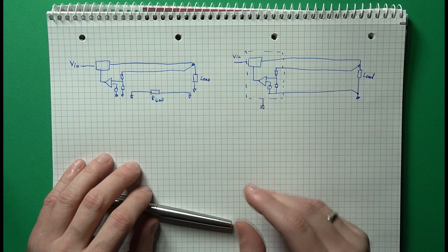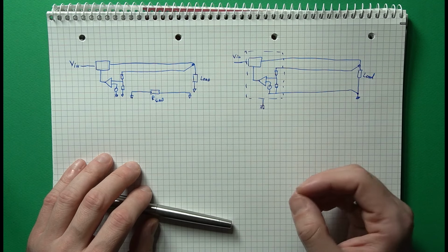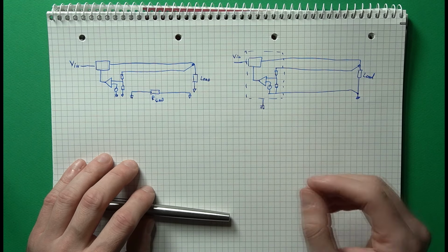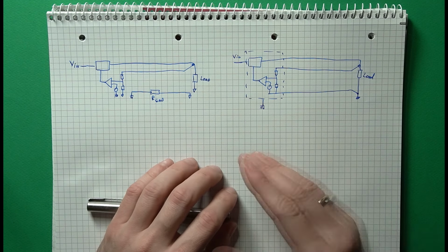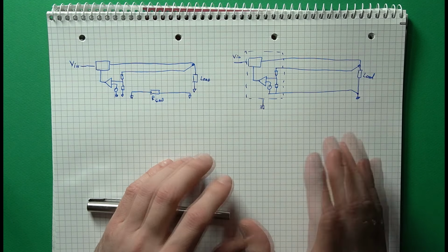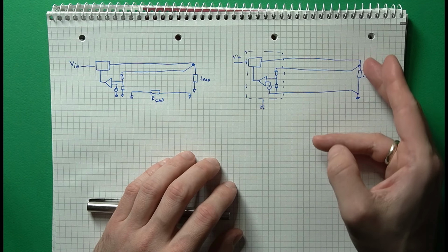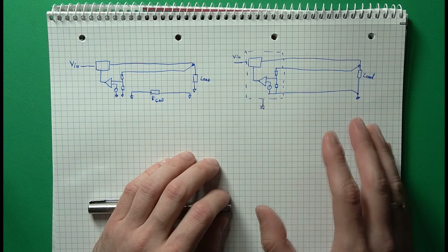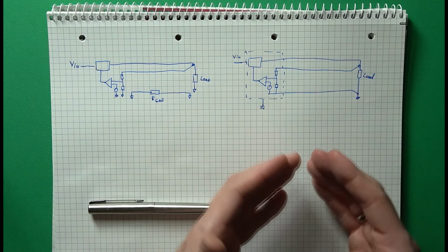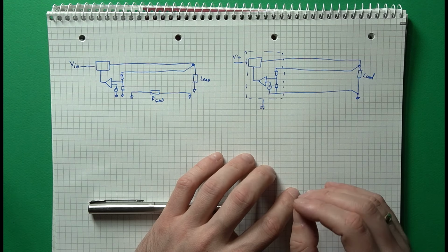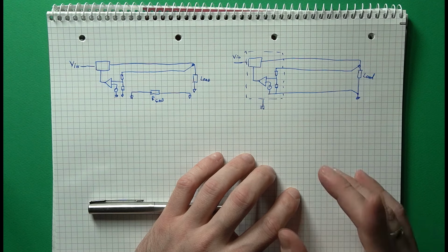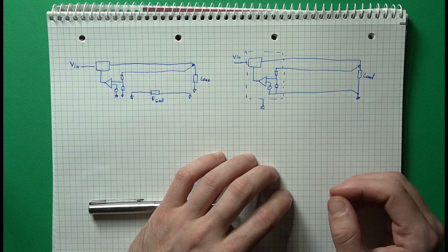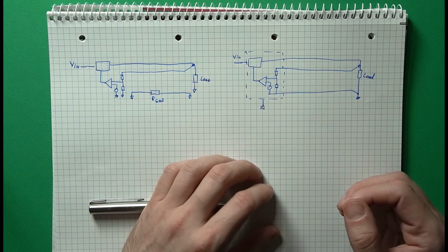The next best thing is to measure both lines at the load. So this will most often be applied when the power supply has dedicated pins for this, and you only want to use these extra lines for sensing. All of the high current needs to run to the supply over different lines. So you will have a dedicated high current positive line and a dedicated high current negative line. This approach ensures maximum accuracy and is usually used when even small voltage differences that could occur would lead to unwanted issues. So normally with very high currents or when the distances are very long.